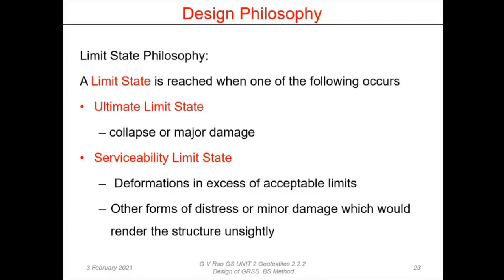The other limit is that deformation is going to be excessive. That means settlement is going to be much more. The wall itself looks intact now, but is settling more and more actually. So that is called serviceability. So basically what you mean is that a collapse or major damage is going to occur because of the strength portion, and here the whole wall is going to settle. Essentially settlement may not be much in the wall itself, but settlement is also more because of the subsoil conditions.